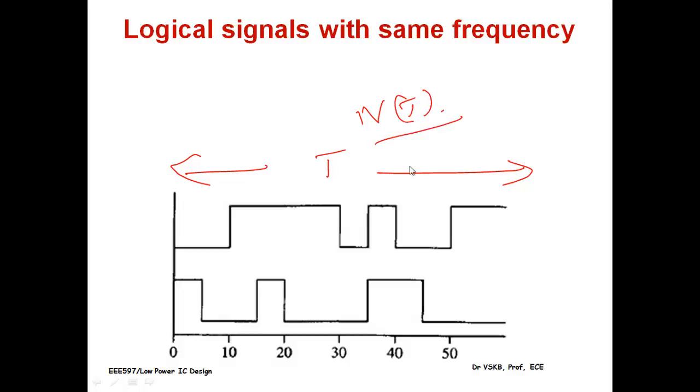And if I am finding the average, I would very simply say it is divided by t, but I am not going to call it divided by t, because one frequency, if I say it is one cycle, has to have a positive transition and a corresponding negative transition also. So I would put this as n of t by 2t when I consider the observation time as t. Therefore, we specify f is equal to n of t by 2t,